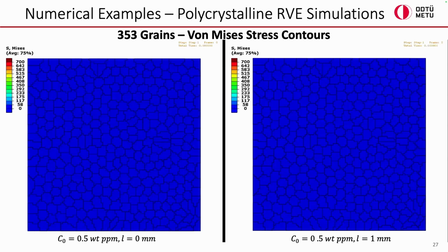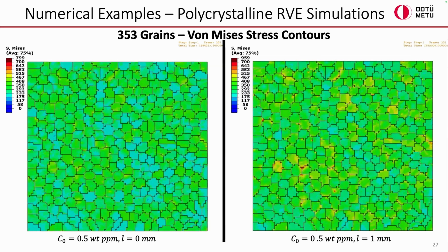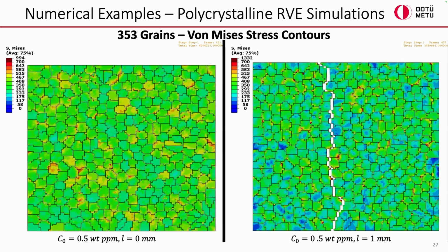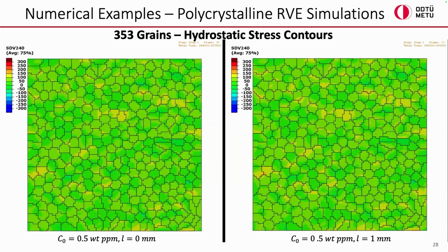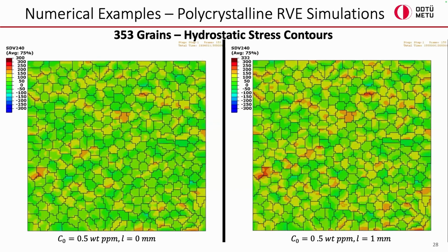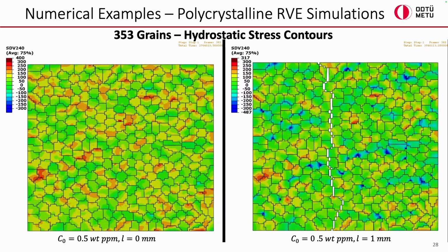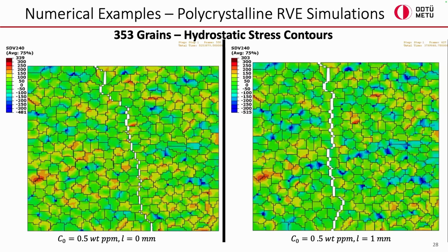In this case, the deformed stress contours also showed a slight increase in the stress, but a crack path change between the local and non-local models. As we can see, the downside of the crack changes. This is the hydrostatic stress contours. Again, as the non-locality increases, the hydrogen concentration increases, such that hydrostatic stress concentration is increased due to the effect of the increased overall stress.